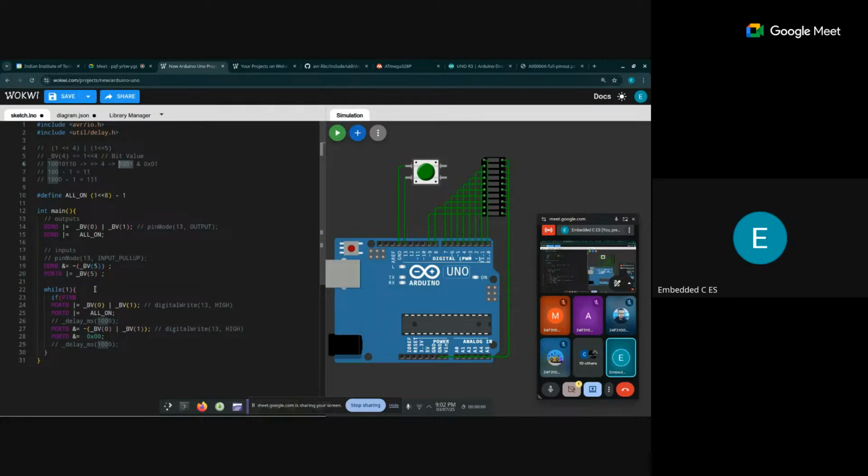So to check a particular bit, we take this register, right shift it by the bit number we want, we want to check the fifth bit, and then AND it with 0x01, which is basically 1 at the end and remaining all zeros. So this will check whether that particular value is true or false.